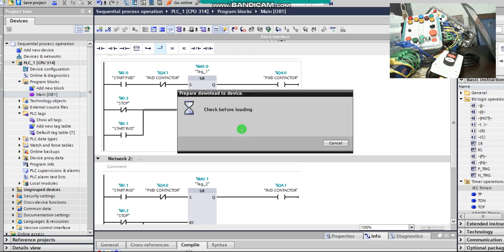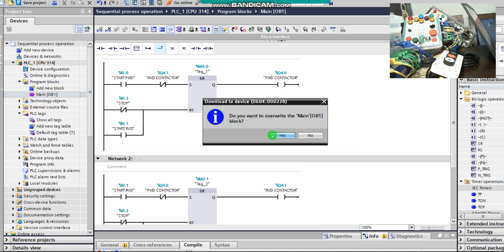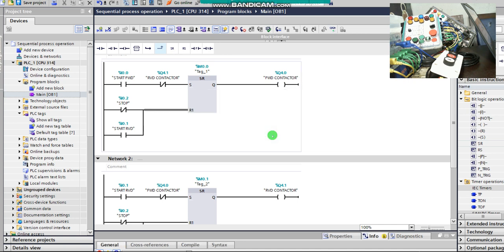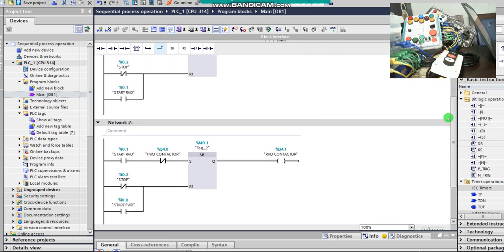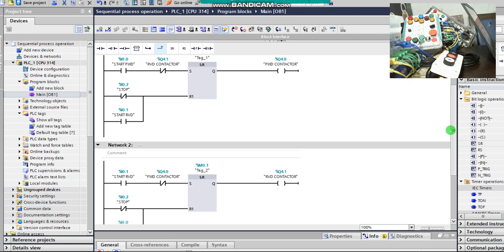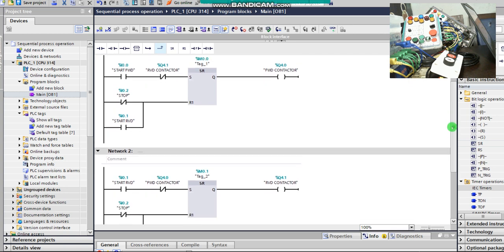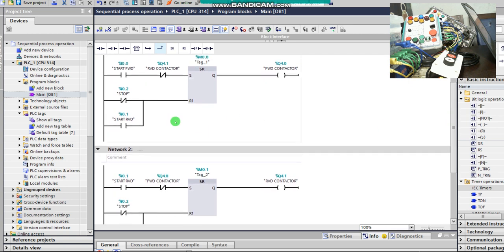Because if I open my gate and my gate is opening and I discover that I no longer need the gate to be open, I want it closed, I can't be waiting for the gate to open fully before I initiate the command of closing. So I can override that opening and close it back by adding this particular additional logic, so that whichever direction operation is initiated, the second operation can override that same function. That is what I have here now. All right, let's test once more.